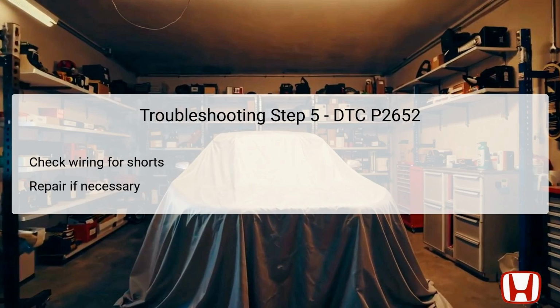First, disconnect the rocker arm oil pressure switch 2P connector and begin inspecting the continuity between the designated test points. This procedure is necessary to determine if there is an unwanted short in the circuit. Conduct the tests under the condition of the vehicle being in the off or lock mode.